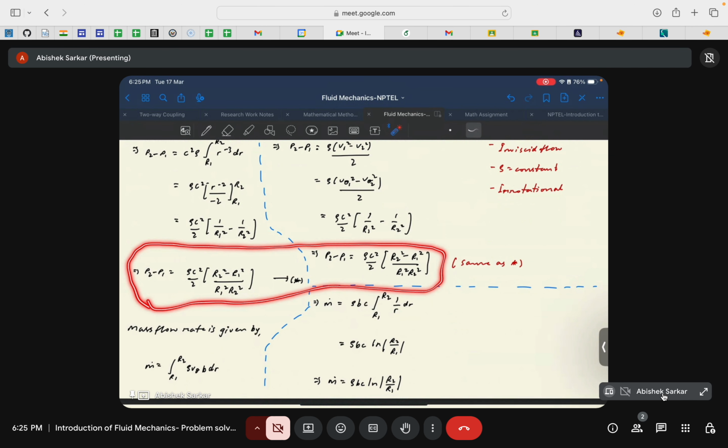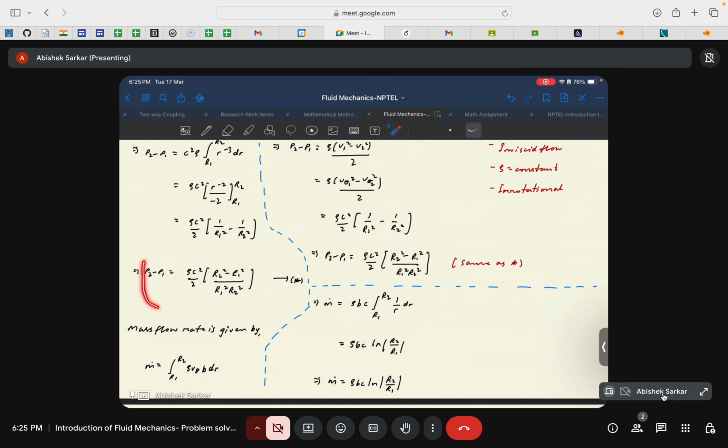So we found this out without having any idea whether we could apply Bernoulli's equation or not, and there's no harm in doing that. You started with the right fundamental principles. You know that Euler's equation of motion governs this kind of flow. If the flow is inviscid and steady, you know the governing equation for that kind of flow. But you saw that there are some inherent difficulties: if the geometry was a bit different, you would have to find the proper coordinate transformation to solve this equation. That's what I wanted to imply.